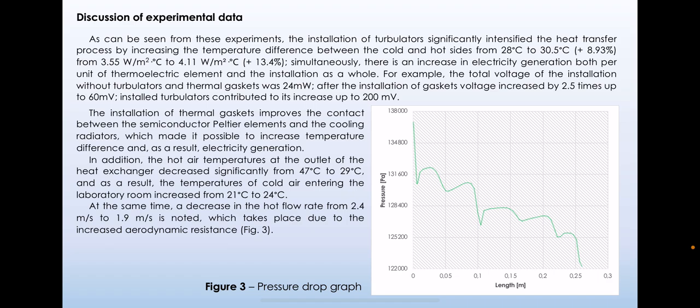Discussion of experimental data. As can be seen from these experiments, the installation of turbulators significantly intensified the heat transfer process by increasing the temperature difference between the cold and hot sides from 28 degrees to 30.5 degrees.